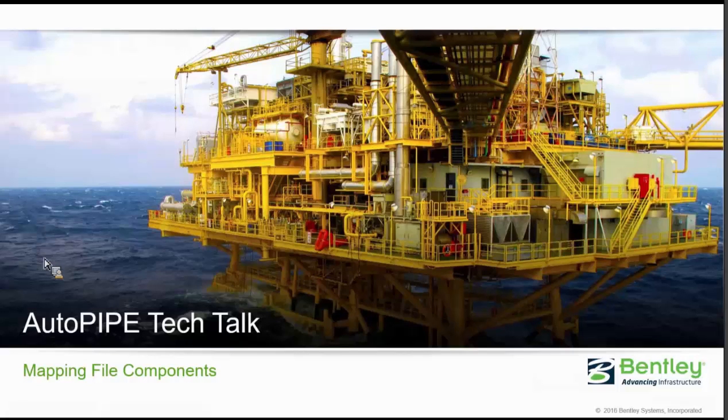In watching the import process there may have seemed to be a lot of manual inputs required. A lot of these options can actually be taken care of in the mapping files that are used to create the AutoPIPE DAT model from the OpenPlant or AutoPlant PXF file.